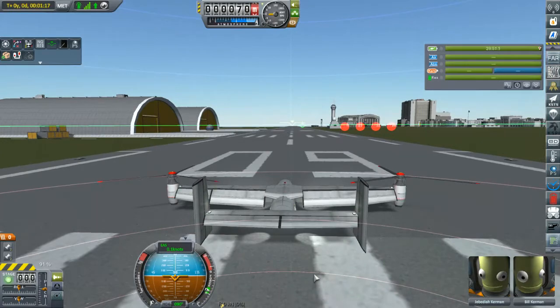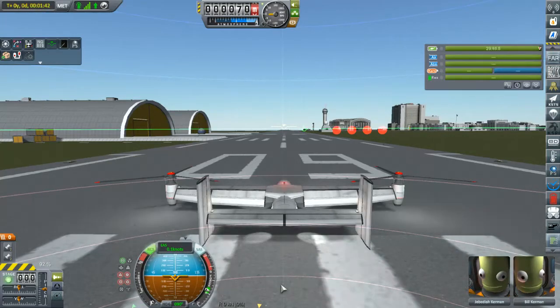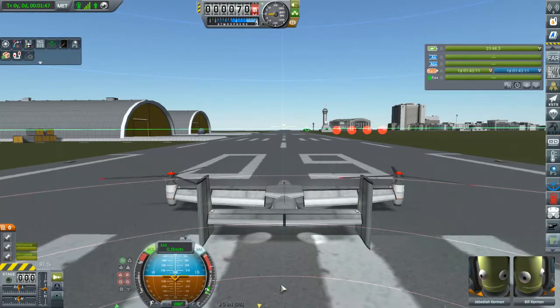Now the next thing we need to do is, because this is a rotorcraft and we don't have simulated gyroscopic physics from the discs, we do want SAS for stability. Gyroscopic stabilization is actually a thing with rotor-based equipment. Spinning things tend to not like changing directions, which means helicopters actually don't like to start to drift into rolls. At least not too much, unless their thrust is just offset. And now let's start the engines. The sound effect you're hearing is actually custom.